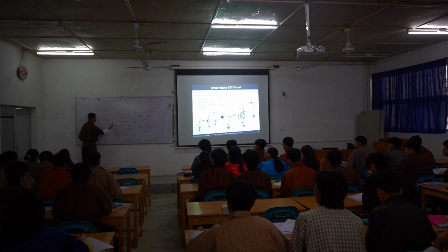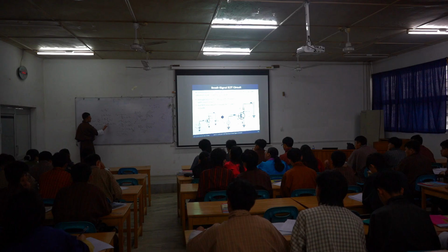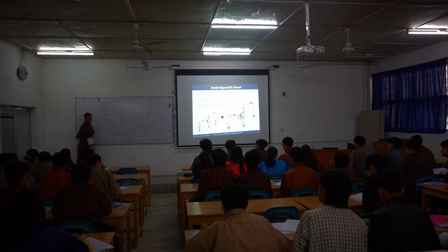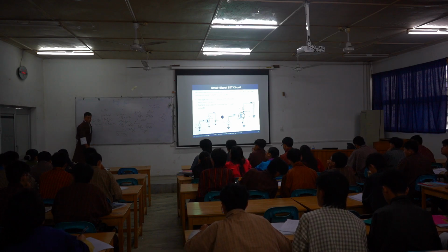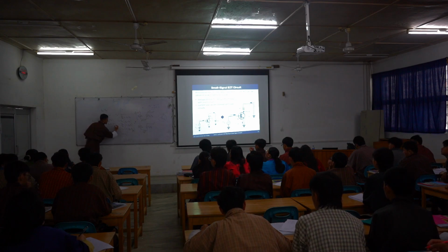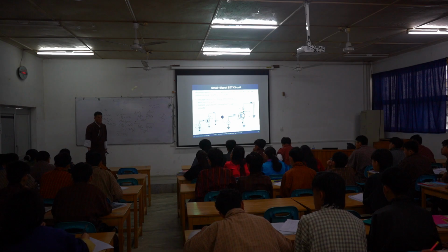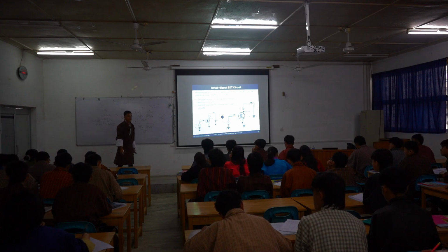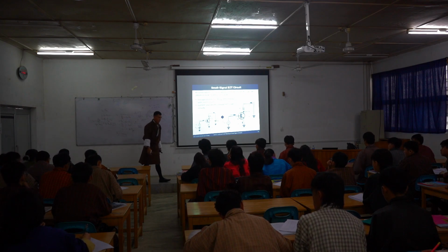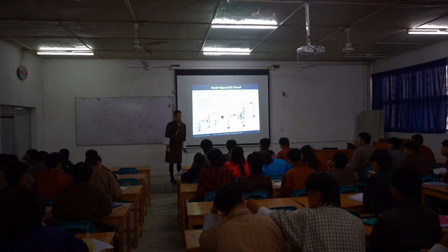So if you substitute R pi, then the two GM get cancelled and you will get GM times VBE, which is also equivalent to beta times IB. Okay, these are the three configurations that you will see as the representation of the hybrid pi model.